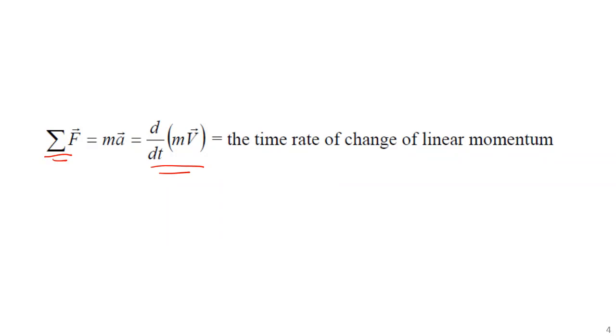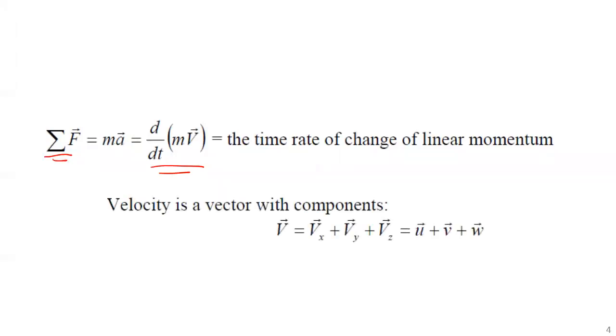And a way to represent that mass times acceleration is basically the change in linear momentum from where this flux is entering to where it's leaving. And actually, that's what we're going to do when we talk about momentum. So again, all we're saying is that the sum of the forces is the time rate of change of linear momentum for the fluid. And we also want to recognize that whenever you see this capital V with the little arrow over the top of it, that's the velocity vector, just like A was the acceleration vector before when we looked at finite fluid masses subjected to acceleration.